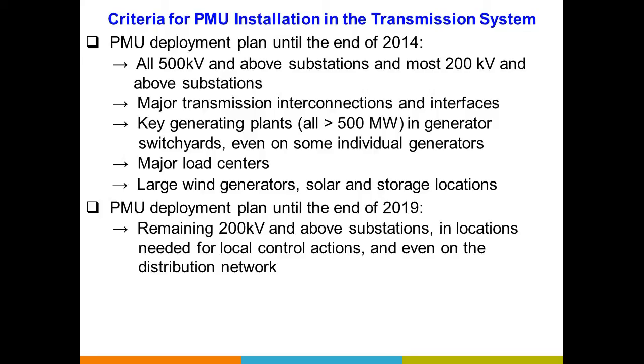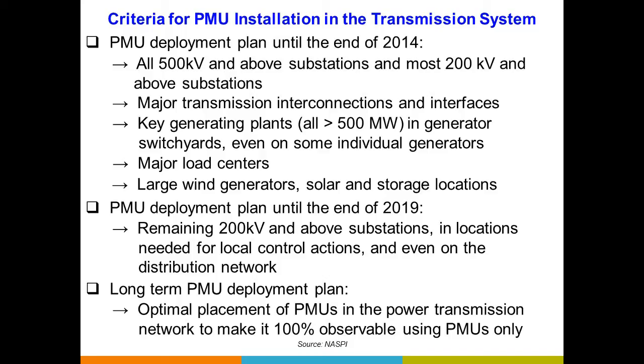And then there is some more research that is going on, and that's probably a long-term plan for PMU deployment, and that is optimal PMU placement in such a way that you can make the entire power system 100% observable using PMUs only. That would be the time when we can reap a lot of benefits from the Synchrophasor technology. That is the time when we can realize how powerful this technology is, if we can get our entire system covered with PMUs. Well, we are progressing towards that. Hopefully this time comes soon in the future.